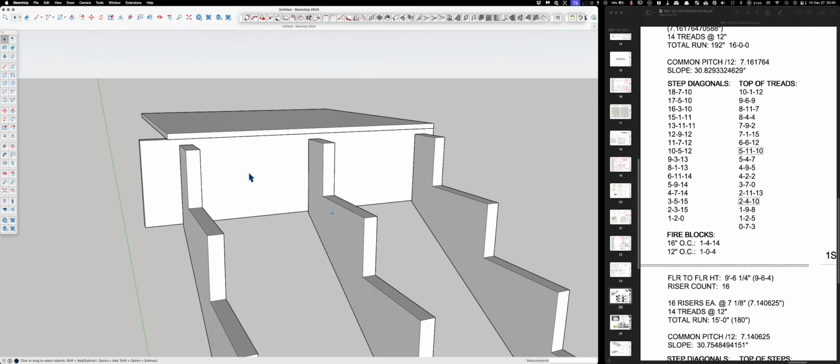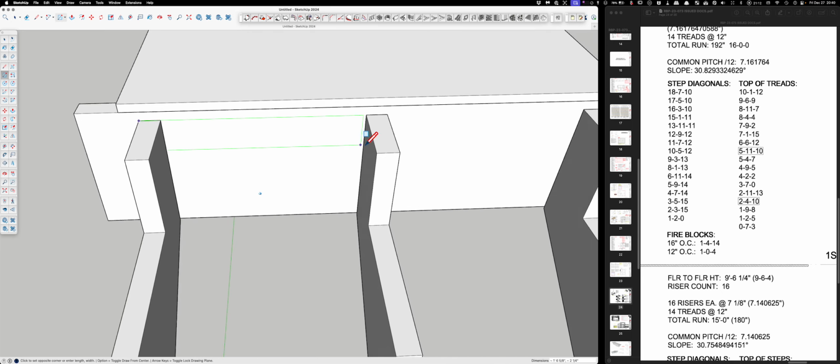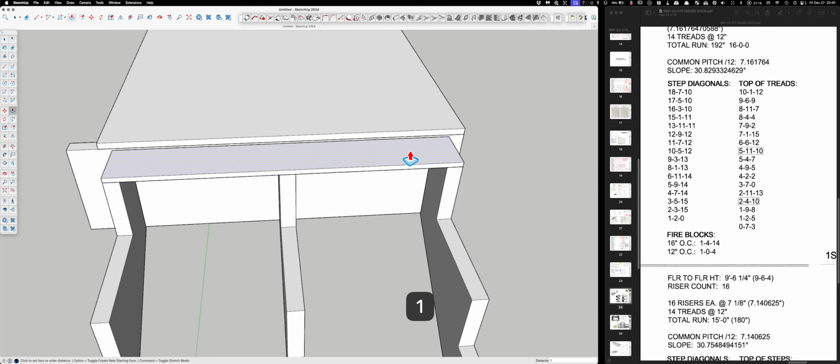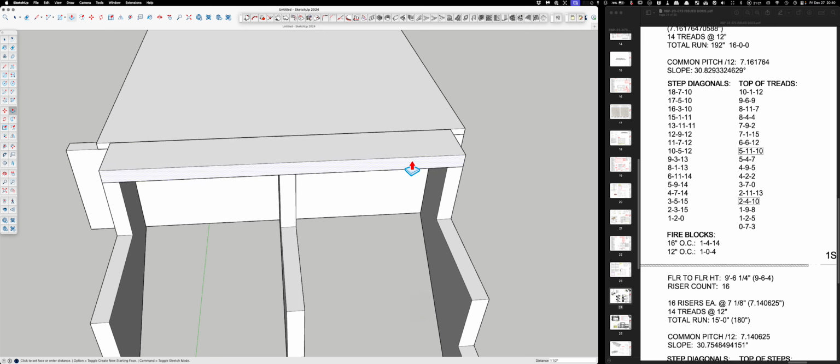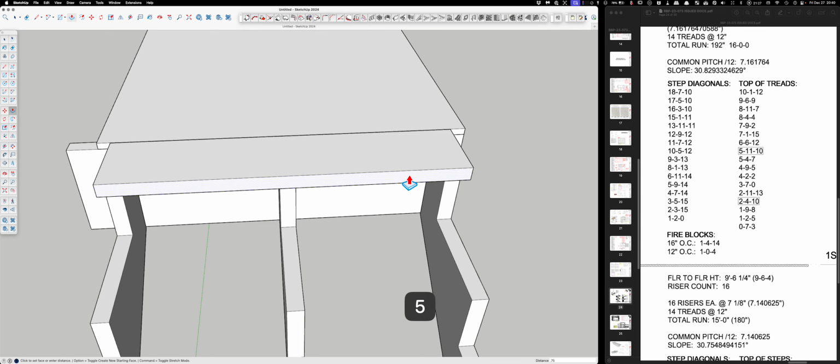Okay. And then rectangle. We're going to go like this just to do it kind of quick. P up 1.5. This is going to go 1.5. But then it's going to have a 3/4 nosing, 0.75, enter. Okay, so there's the tread.